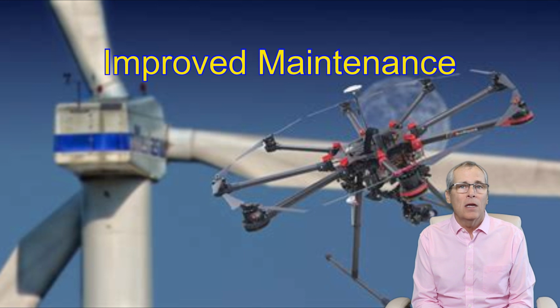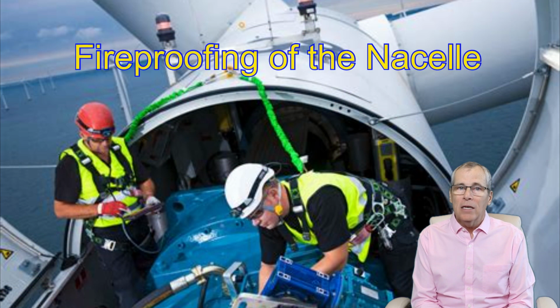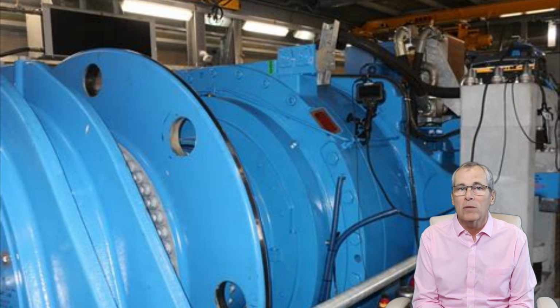Improved maintenance and inspection. Regular maintenance and inspection of wind turbines is crucial to minimize the risk of fire. Many companies are now using predictive maintenance techniques such as thermal imaging and vibration analysis to detect potential issues before they lead to a fire. Fireproofing of the nacelle. The nacelle is the most vulnerable part of the turbine. The industry is developing fireproofing methods for the nacelle, such as using fireproof insulation materials or applying fireproof coatings.